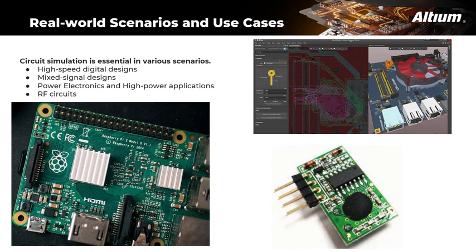And lastly, RF circuits demand precise control of signal frequencies and phase noises. Simulating RF designs, such as Colpitts oscillators, allows engineers to assess the impact of component variations on frequency stability and optimize their designs to achieve the desired performance. Monte Carlo analysis, in particular, can be instrumental in understanding the effects of component tolerances on the overall circuit behavior.